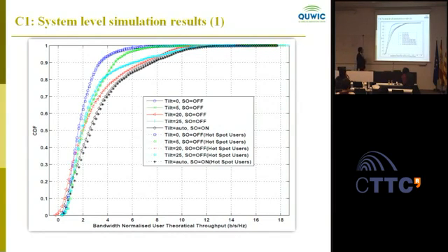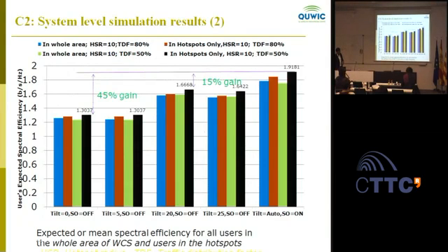So you gain, it depends on the location of hotspots, but on average, in this simulation the hotspots are randomly located, and it's a 51 cell network. So you can have some substantial gain in spectral efficiency just by adjusting the tilts of 3 adjacent base stations. If you want to look at the numerical values, compared to no tilting you'll have almost 45% gain. And compared to, say, traditionally optimal tilting for that particular network layout, which your ordinary planning tool will give you, you will still have 15% gain.